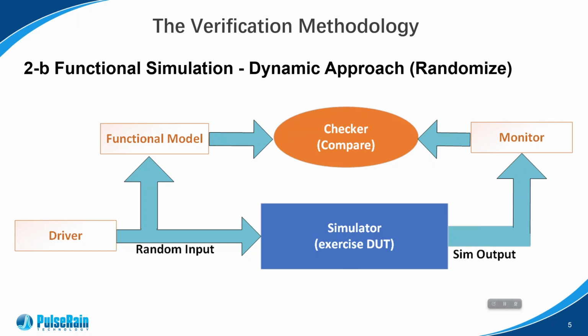Another approach is called dynamic approach, for which the input is randomized, and the simulation output is compared against a functional model, as shown in this diagram. The driver will generate the random inputs, and the monitor will capture the simulation outputs in the diagram.